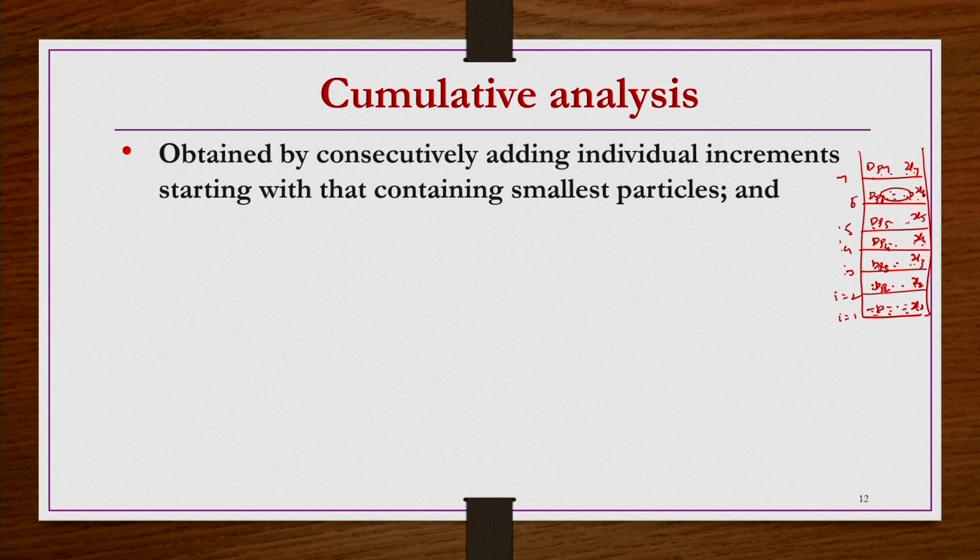So, now for cumulative analysis, for the dp_7 row, the cumulative fraction x_7, what is the fraction of material that is having the size smaller than dp_7, right. So, this cumulative analysis is actually of two types, cumulative oversize and undersize, right. Undersize we will say, like dp_7 first we take, so in the column here. How do you find, against dp_7, what the cumulative fraction should be?